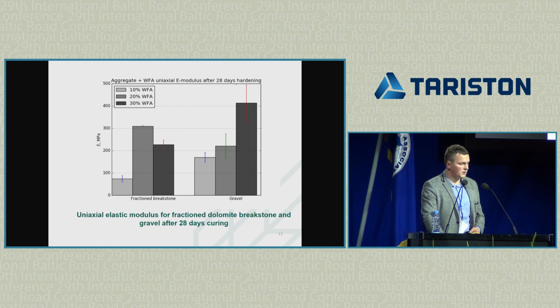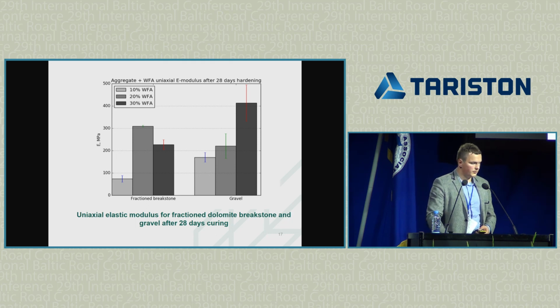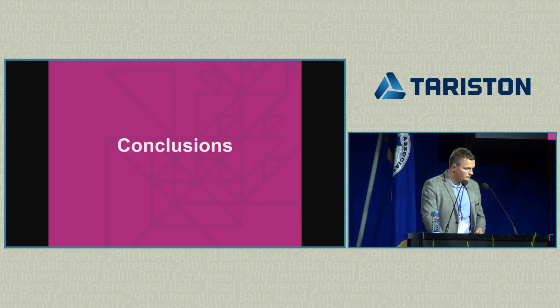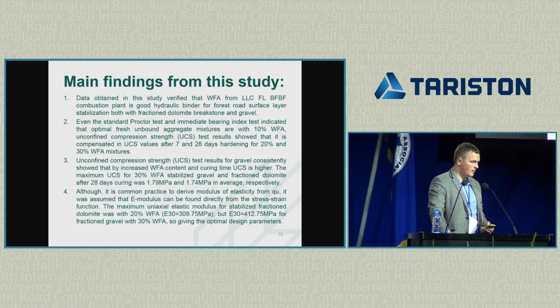I think we succeeded, you can see the values here. For the gravel, it's even about 400 megapascal. We're still considering how to use those values for the design, but definitely we're not getting weaker material, we get stronger material here.